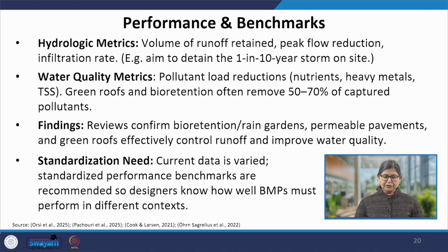Water quality metrics, pollutant load reductions for nutrients, heavy metals, total suspended solids, etc. Green roofs and bioretention often remove 50 to 70% of captured pollutants. It has been found that reviews are confirming bioretention or rain gardens, permeable pavements, or green roofs effectively control runoff and improve water quality. So, also they control the sediments.